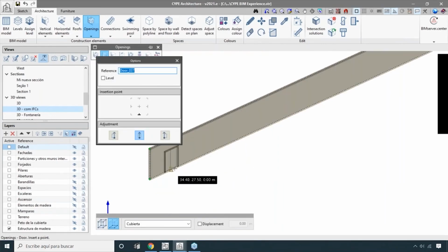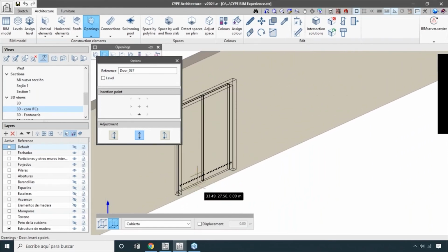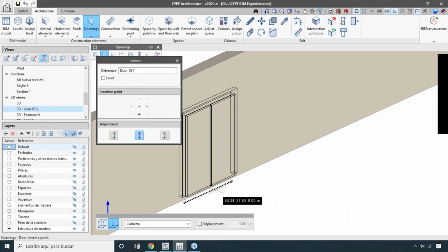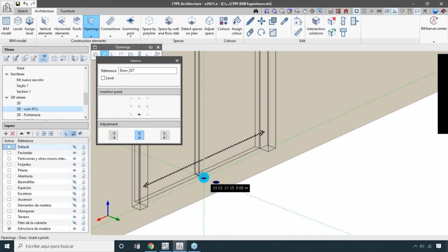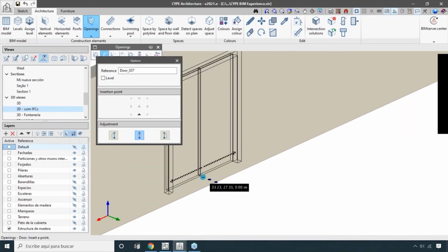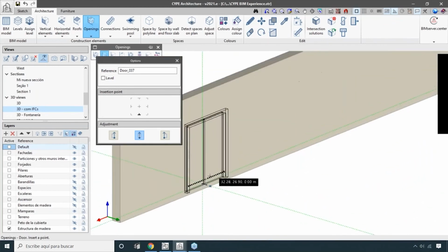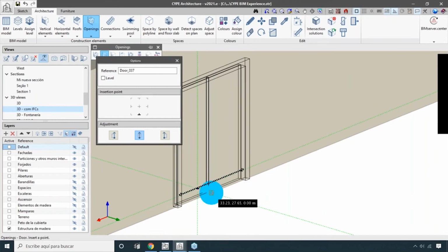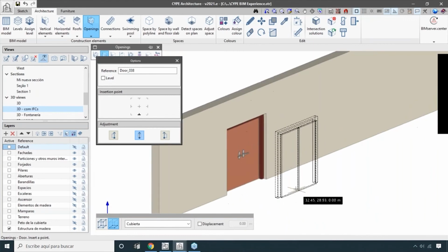Okay. For example, I will put this door 4 meters from this point here, 4 meters. Now we must select the opening position. Okay, so this door could be in this situation or in that situation. So in that situation, for example, and then we can put it on one of the surfaces of the wall. Okay, the internal surface, for example, in the middle or in the external surface of this wall. So let's suppose it's in the middle. So this is the wall.